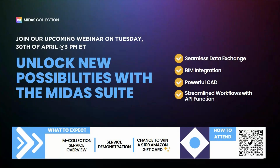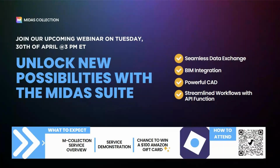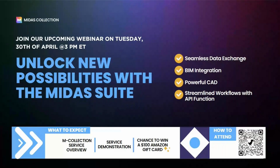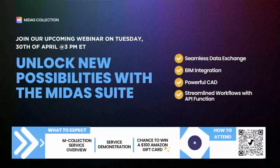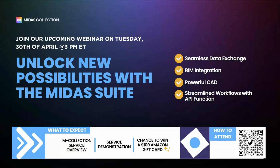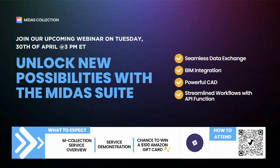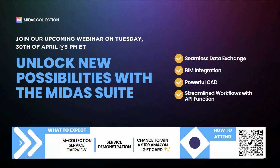Is the seismic design based on the AASHTO force based method or the AASHTO displacement based method? As of now it is the AASHTO force based method, but we are working on the AASHTO displacement based method as well. You might be seeing some webinars we are having from the same philosophy, talking about these design approaches. The idea here is that the displacement based method can also be achieved in the program. You have the definition of hinges, and you have the capability to give different moment rotation hinge curves. So the displacement based method can also be availed in the program.